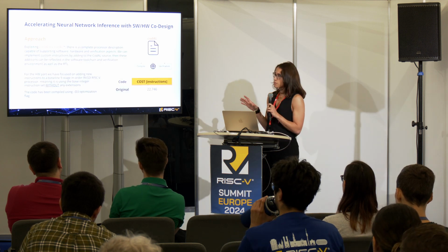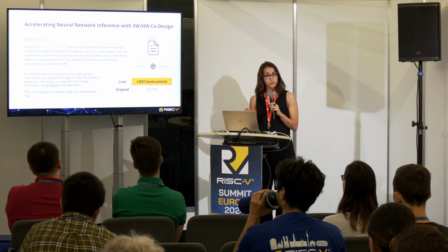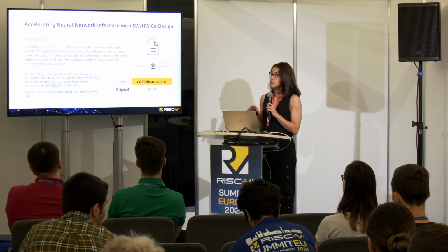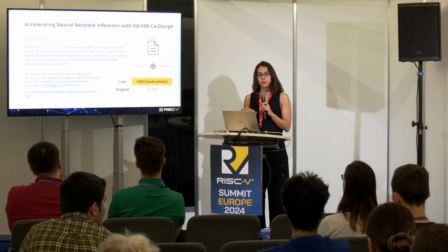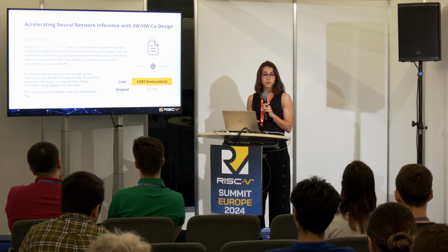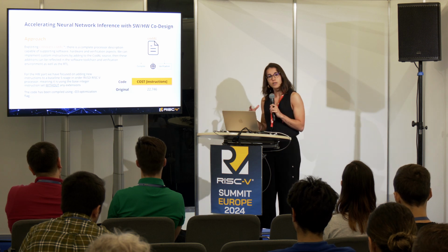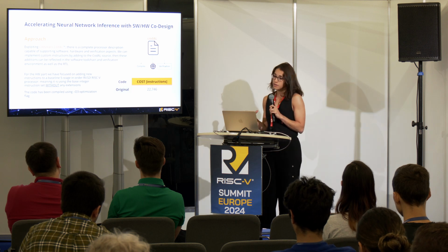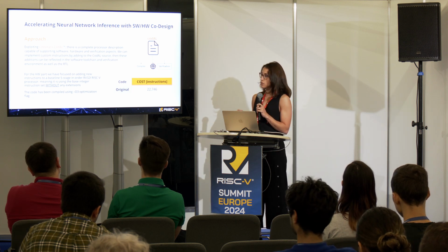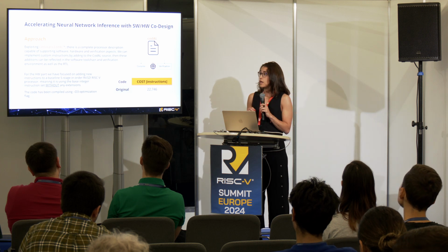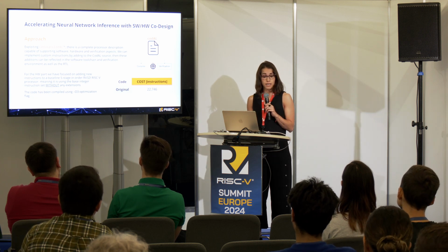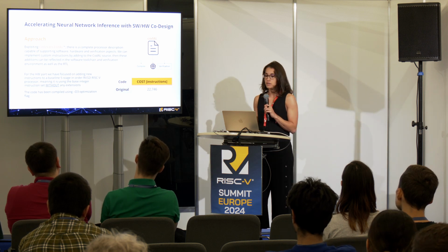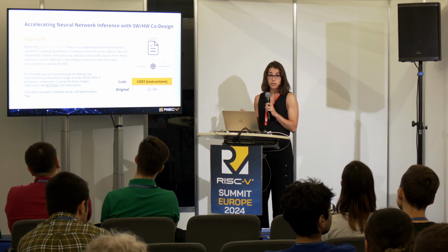We can concentrate a little bit on the method that we needed to use in order to accelerate the function, which was exploiting the Codasip tool and in particular the CodAL language, in order to have a complete description of a processor and introduce a new custom instruction that was easily introduced in the system and compiled with the SDK. So we had a RISC-V 5-stage in-order core processor with a base integer instruction set without any extension, and the entire system was compiled with an O3 optimization level, achieving a number of instructions that was, for everyone, the beginning,